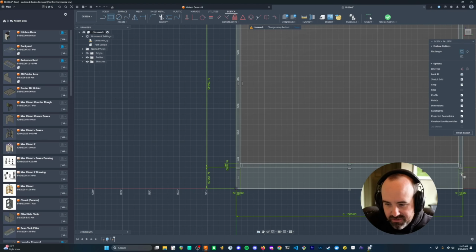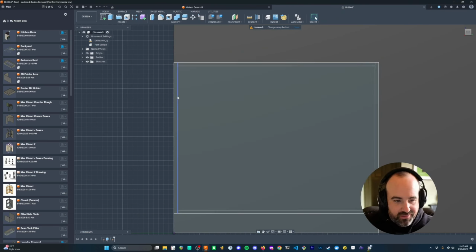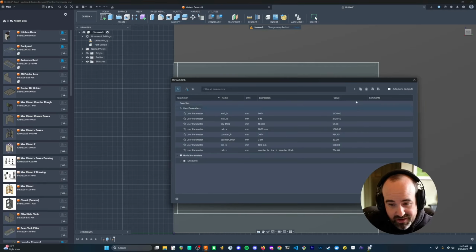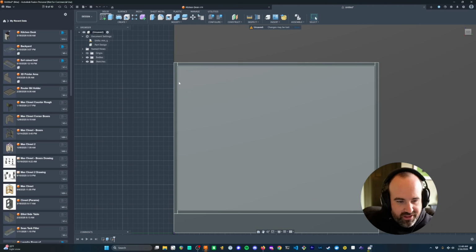So usually when you build a cabinet box, depending on how you want to do it, you do a solid base on the bottom, solid pieces on the sides, and then what are called stretchers across that are not as wide, and I'll show you that in a second. They are just to give the box strength, rigidity, and actually make it a box. And I'm going to add this as a constraint, which is the stretcher width. Usually I just do 100 millimeters.